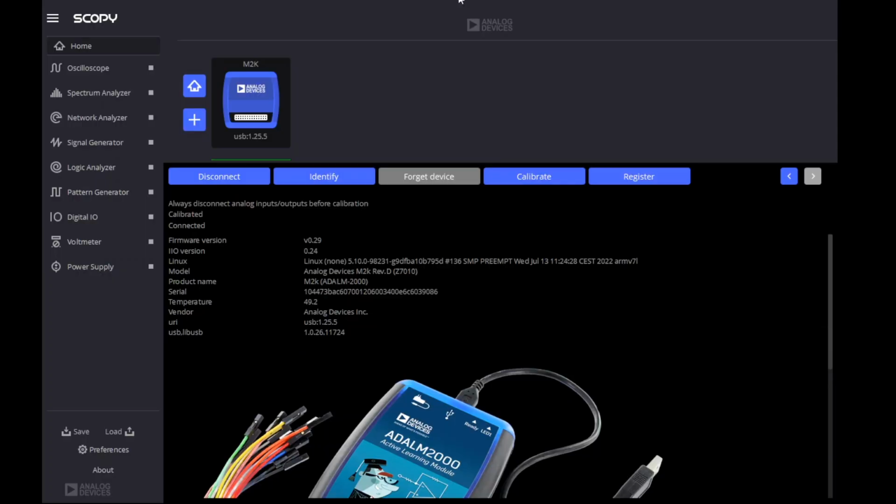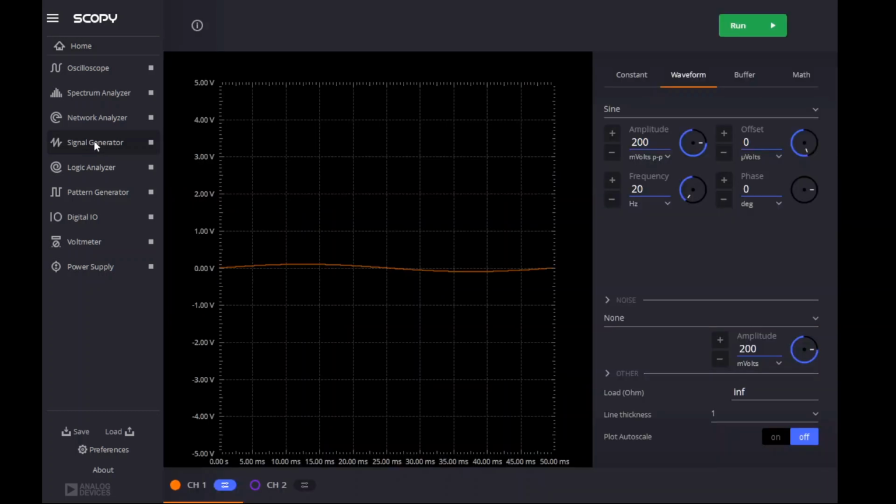So let's go through the test procedure. We have a 5532 from the Bojack kit installed, and R1 is about 47K. So we're in a situation where we expect a gain of about minus 10. To start with, let's confirm that the circuit is working as we expect. So we want to start with a sine wave at 200 millivolts peak to peak amplitude. This is to avoid issues with slew rate that we'll talk about in more detail later. And our frequency is very low.